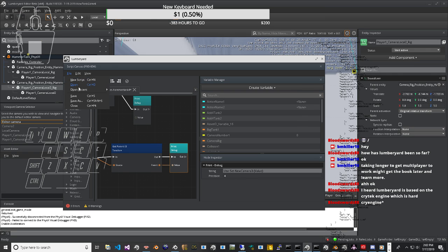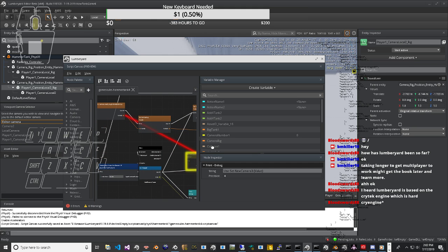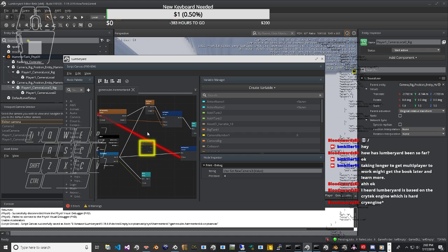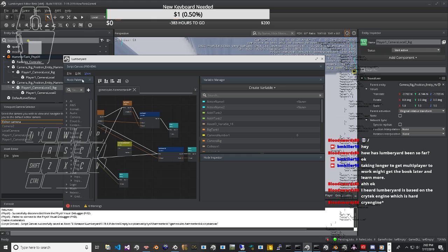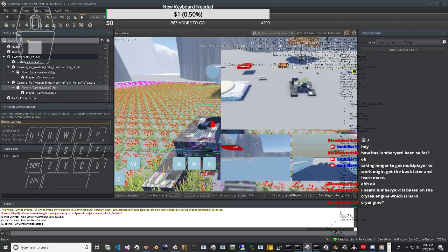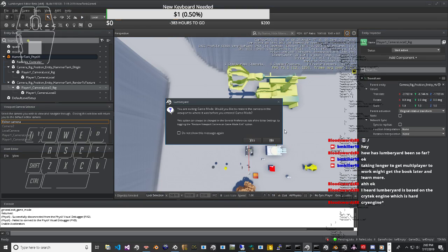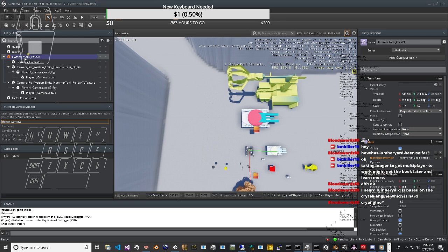In a more or less continuous fashion, the driver compares desired direction, speed, and acceleration with actual direction, speed, and acceleration. The driver uses visual input to sense actual direction and speed, and uses visceral, inertial feedback, the butt sensor, for actual acceleration. When the actual differs too much from the desired, the driver applies throttle, brake, steering, and gear selection to change the actual. These inputs cause the tires to react with the ground, which pushes back against the tires, and through the suspension, pushes the body of the car and driver.